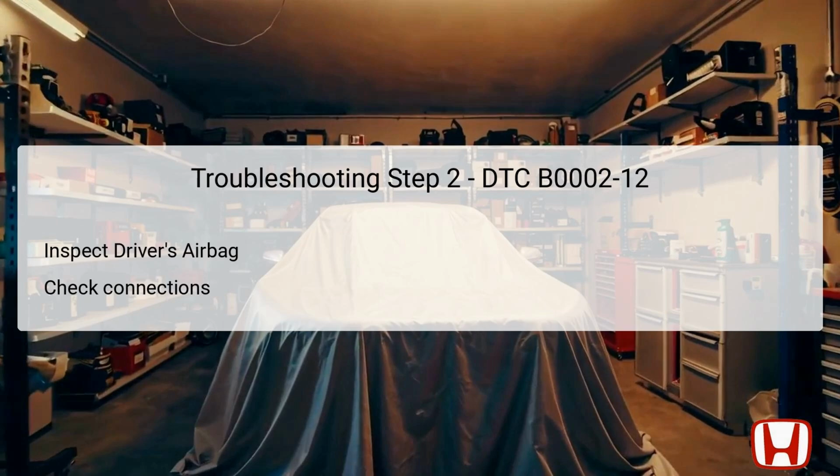In the second step of troubleshooting, we address the driver's airbag directly. Prior to inspection, safety protocols dictate that the driver's airbag second inflator connector, which houses 2 pins, must be disconnected. It's crucial to disconnect the vehicle's 12-volt battery and wait at least 3 minutes to ensure the system is safe to work on. Once disconnected, the technician should inspect the driver's airbag for visible damage, corrosion, or faulty connectors. If the inspection reveals no issues, it's possible that the driver's airbag itself is malfunctioning.